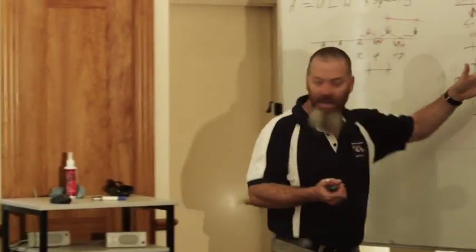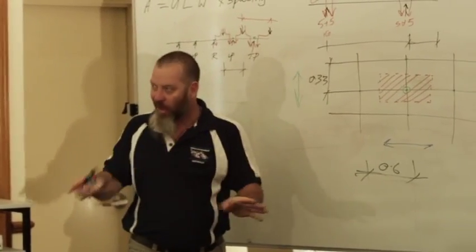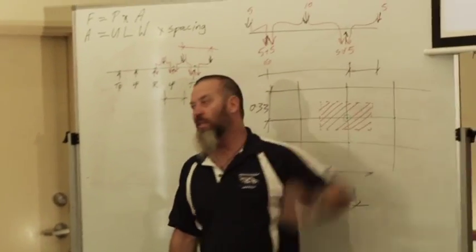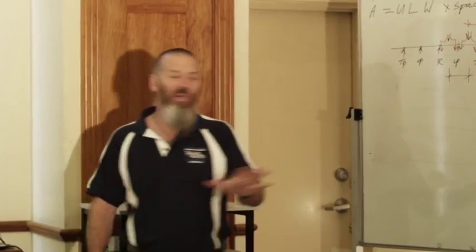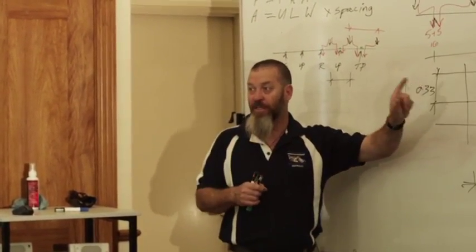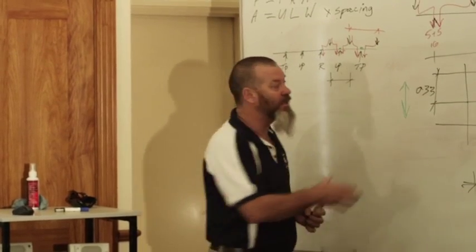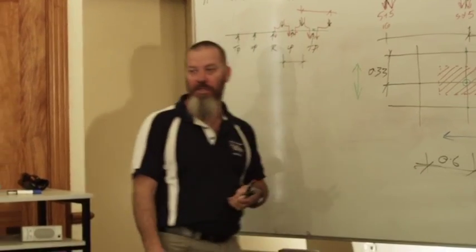Is a batten rafter an outside wall connection? No. So the formula I use is DBC divided by 2 plus DBC divided by 2. So half the distance between connections plus half the distance between connections.